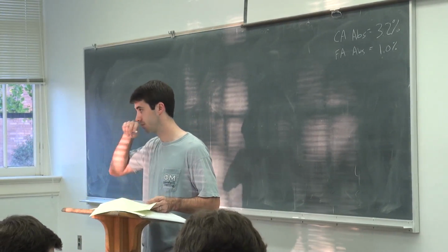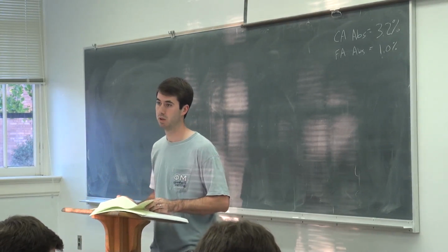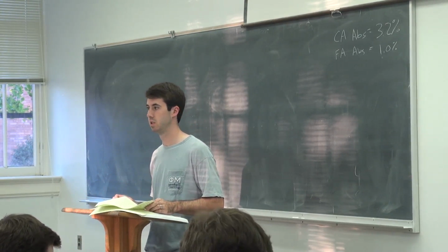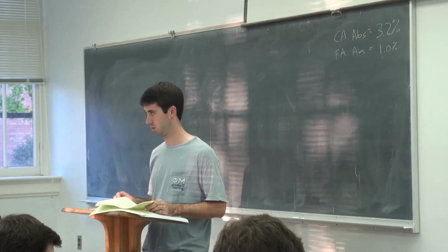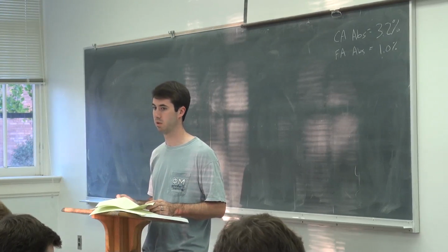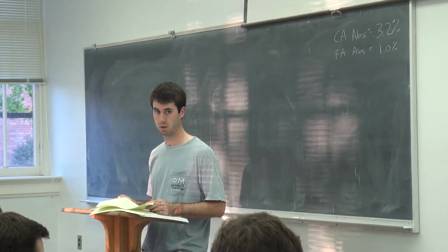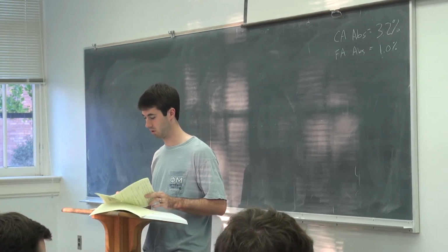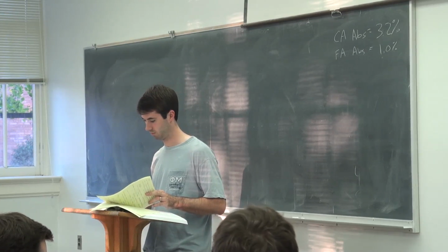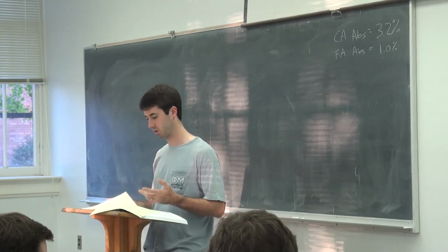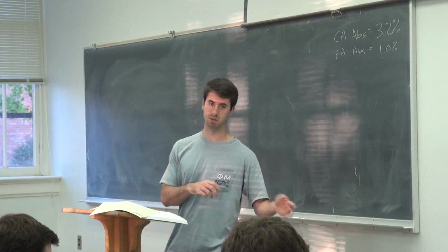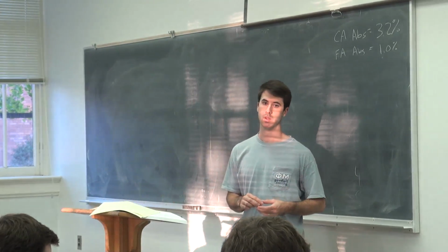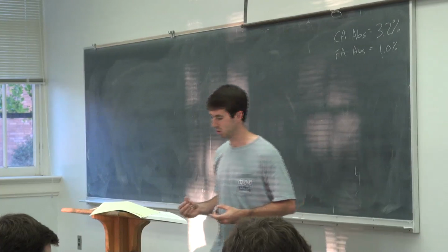Where would we start? Any ideas on what we select first? We're given a water cement ratio, but we skip that step and jump straight to the amount of water we need, based on the slump.